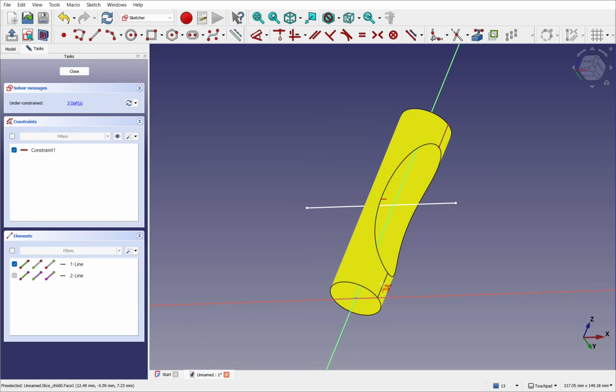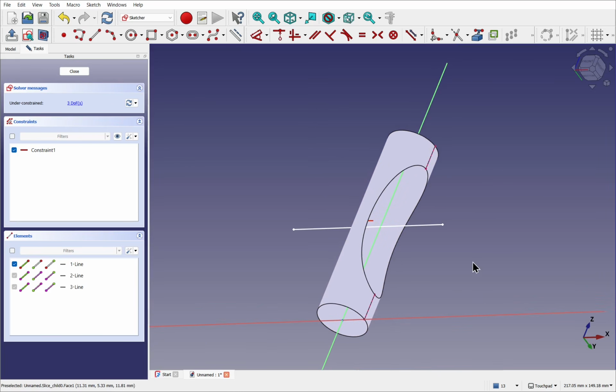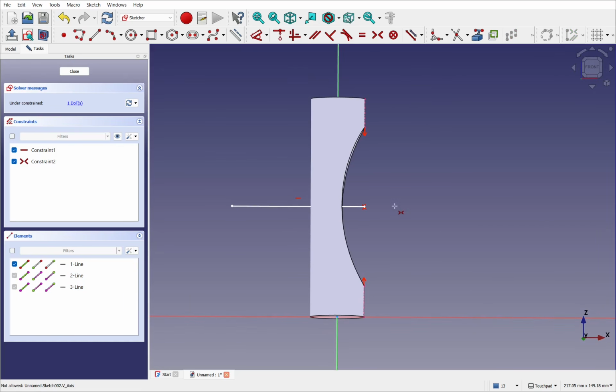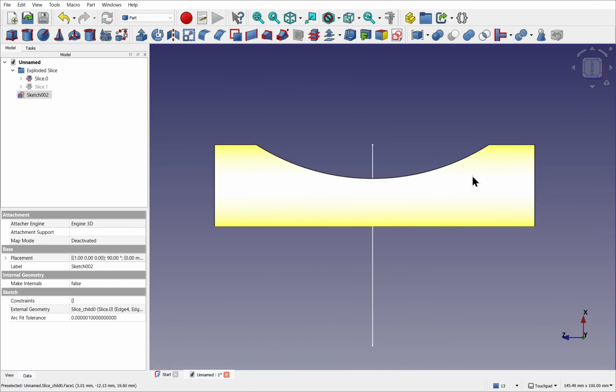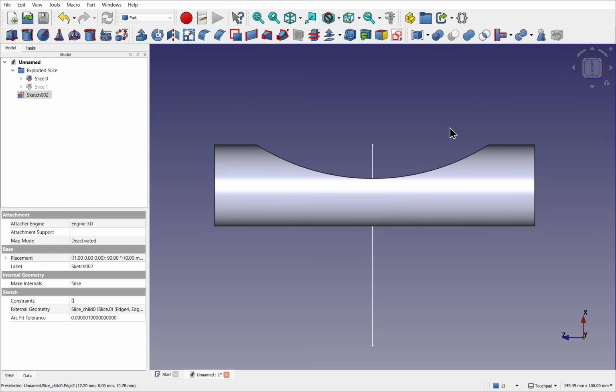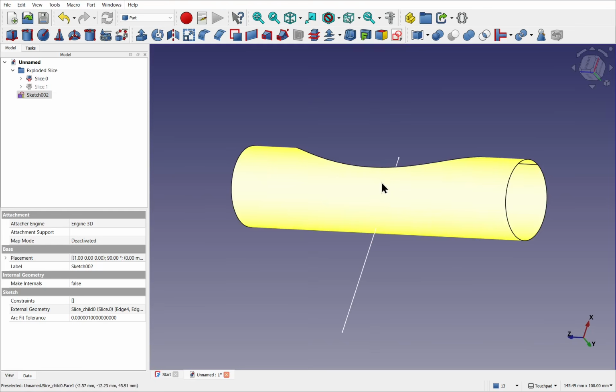Let's take these two lines, right click to cancel, and we're going to use the symmetry constraint, select our 2 points, 1 and 2, and the end point. And that's centered now. Right click to cancel, and close. So we've still got the front viewpoint. This is important because we're going to use the projection now, and we'll project this wire, this sketch, across this object. So across here.